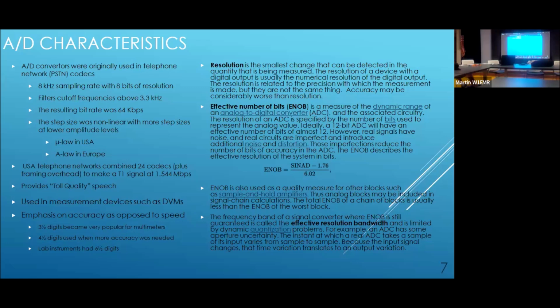Okay. So at a 24-bit A to D, 24 bits times 6 dB per bit gives you a dynamic range of 180 dB. Yeah. Well, don't believe it. That's the technical number, but there are limits. At the lower limits, it's noise, which basically means that your lower digits, the lowest numbers you can measure with it, don't mean very much because they're varying all the time because it's just crud.